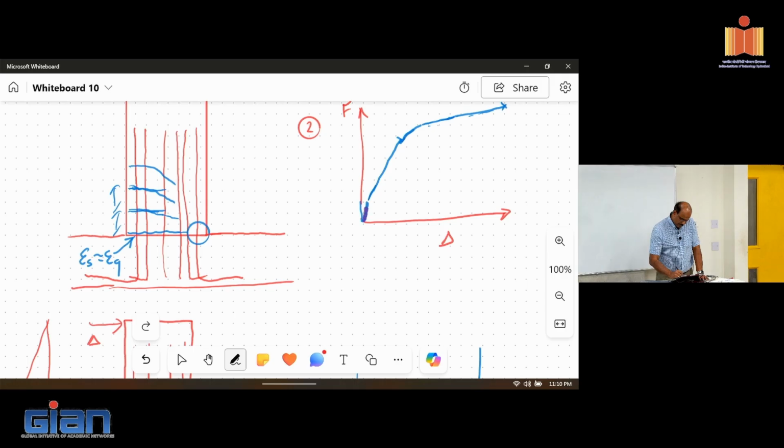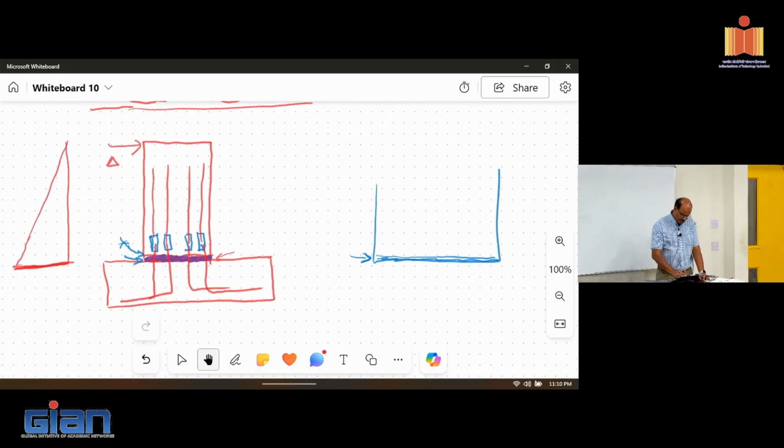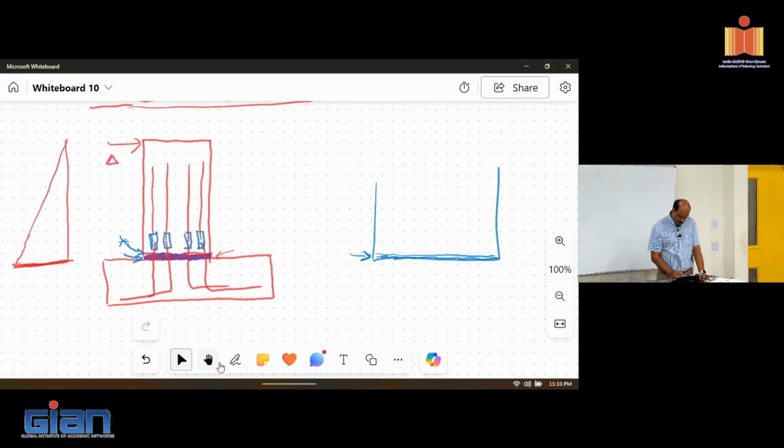It doesn't have to crack at exactly the same load, because your flexural tensile strength may be slightly higher depending on the material used. Sometimes it's lower if you don't roughen those surfaces. But it's going to behave very similarly in the elastic part. There will be some small differences here and there, but I want to go back and look at the crack patterns afterwards.